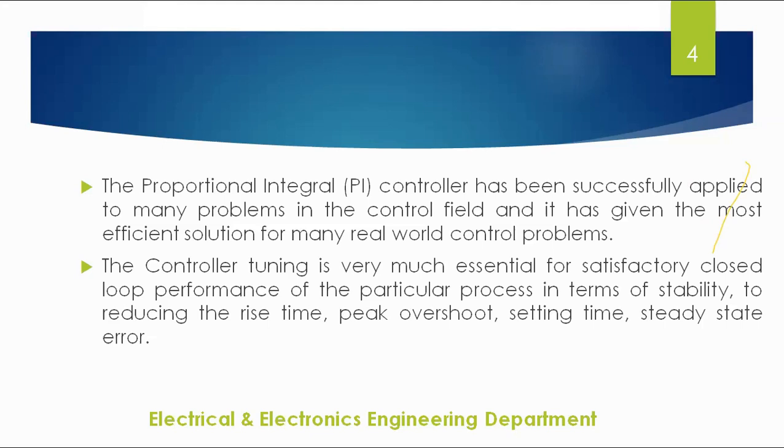Whenever we have a desired performance, for example, the time domain specifications, we can use the root locus technique. We have time domain specs like delay time, rise time, peak overshoot, settling time, and steady state error. Suppose I'm going to develop a good control system, then the controller is very important. Then the tuning is based on our desired spec. Suppose I'm going to refer to time domain specs, so I go for the root locus technique.